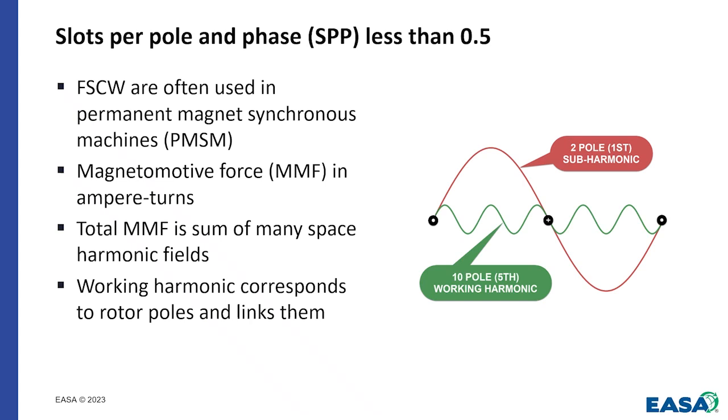In reality, what we've got really is more of a square wave for this one coil going around the periphery of the stator. And the first harmonic, what we call that fundamental or first harmonic, is sinusoidal, but the square wave is made of that plus a slew of other harmonic fields.